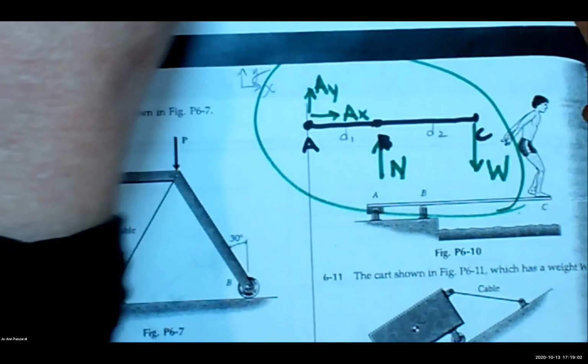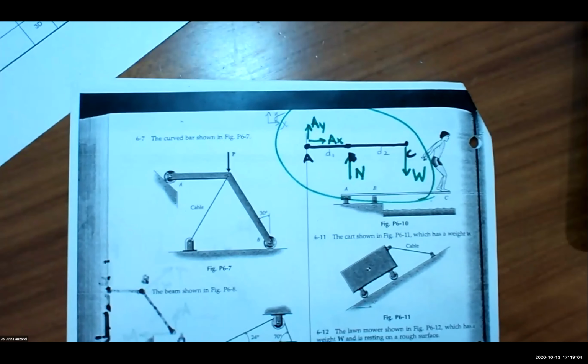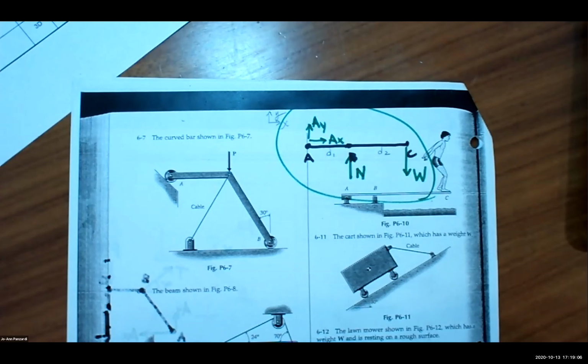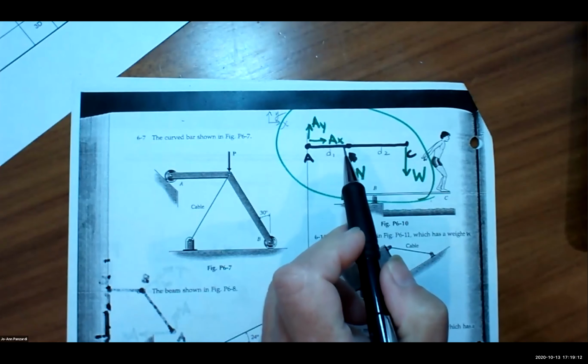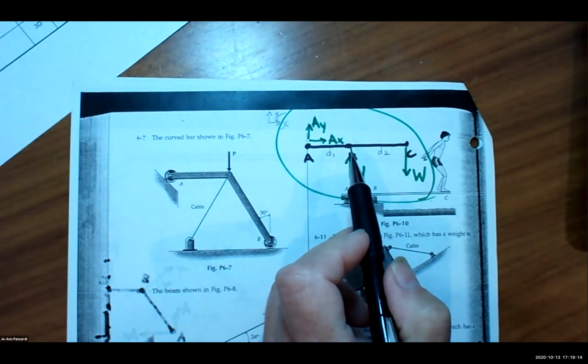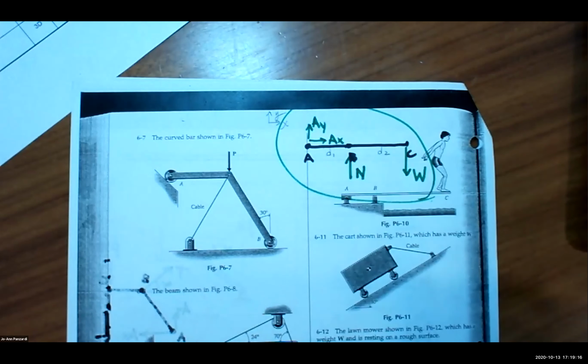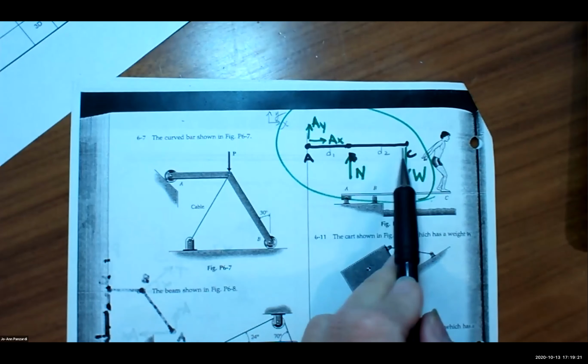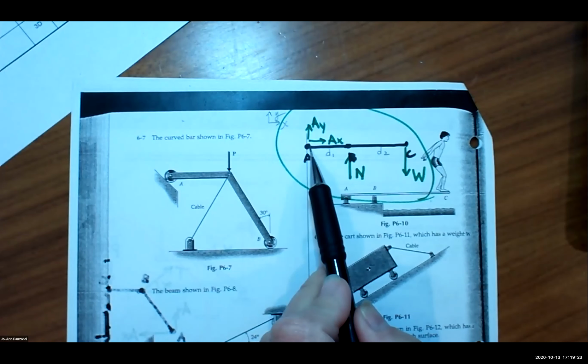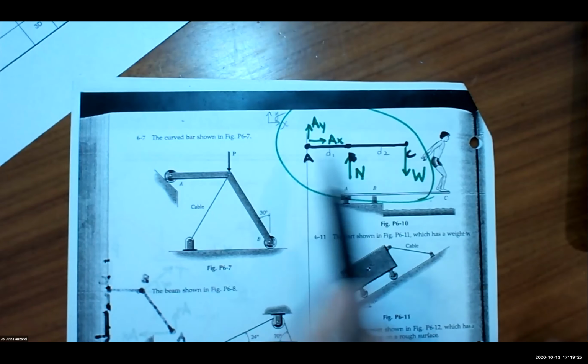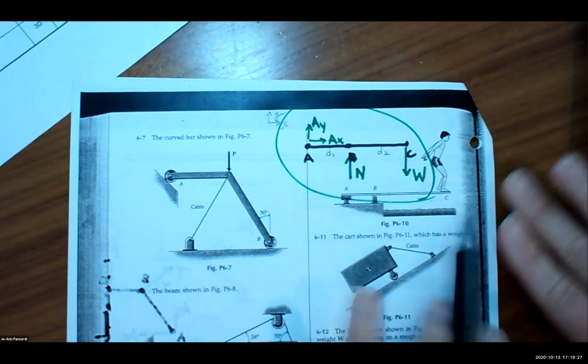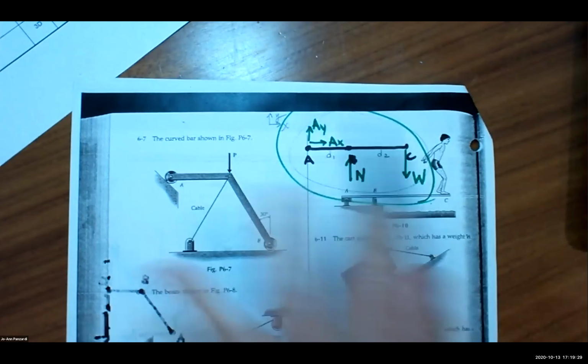There was something that I was impressing upon you when we were drawing free body diagrams before, and it might be more clear now. Notice I am only drawing a free body. Free means it's not connected to anybody. It's free, it's on its own. I'm just drawing the bar, in this case, a diving board. I'm removing it from all its supports, and I'm only drawing forces on it.